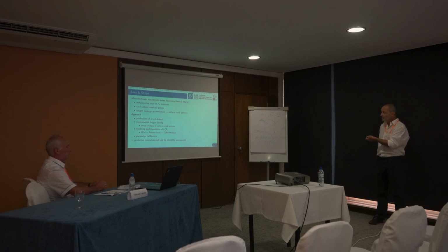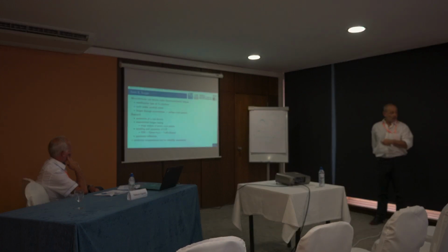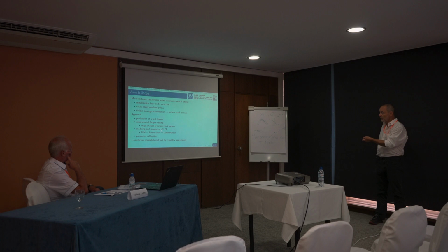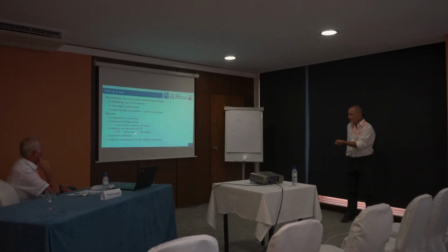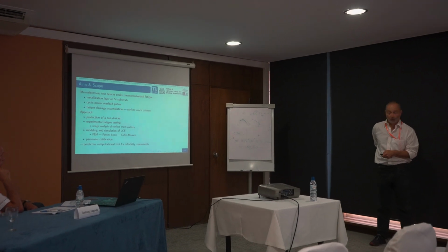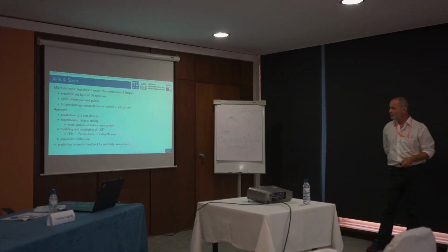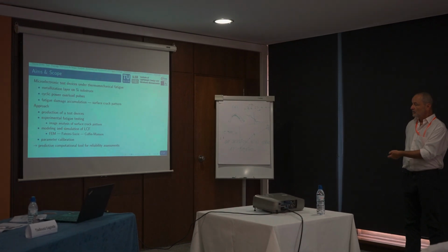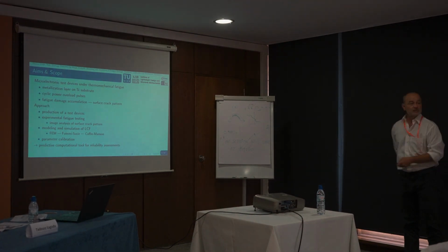The approach: there is production of the test device by Infineon. They do experimental fatigue testing and image analysis of this crack pattern, and our task is the modeling and simulation of low cycle fatigue. Again, a Hoffmann type fatigue law, now in this case without continuum damage mechanics, just the lifetime to onset. And again, parameter calibration. The goal is to develop predictive tools for reliability assessment in microelectronics.